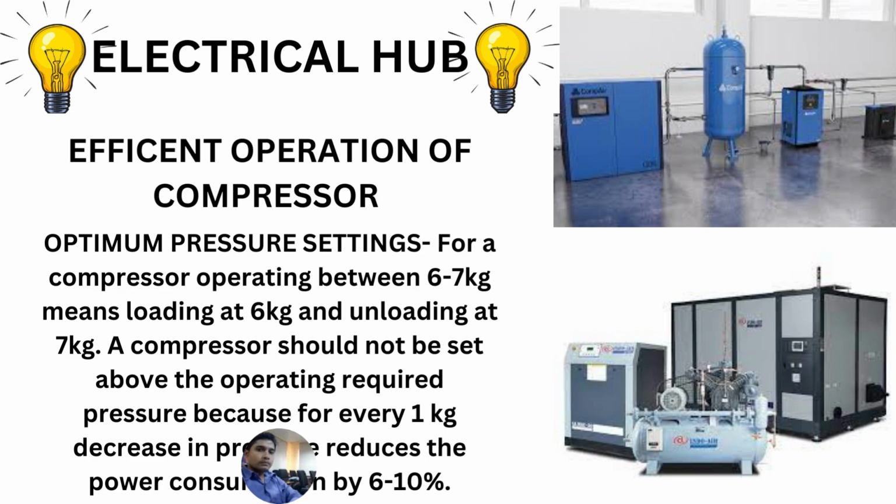Optimum pressure setting. A compressor should not be set at any high value. For example, if you have a requirement of 6 kg of pressure and you are setting the value at 8 kg pressure, it is an unnecessary loss for the compressor, because for every 1 kg reduction in the pressure of the air, the power consumption reduces by 6 to 10%.